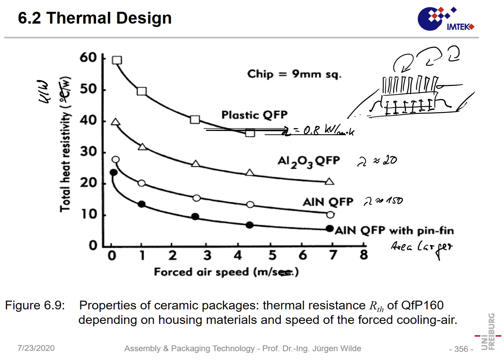And in that way, we can decrease the thermal resistance significantly, but in the end, however strongly we blow, we never get the thermal resistance to 0. What's the reason? Even if the outside thermal resistance, which is the thermal resistance sink to ambient, would be 0, the internal resistance, junction to case and case to sink, would still be there. And in that way, there will always be a residual thermal resistance.